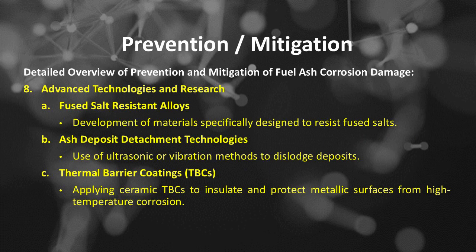Number 8 of prevention and mitigation of fuel ash corrosion damage is advanced technologies and research. Number A, fused salt-resistant alloys. Development of materials specifically designed to resist fused salts. Number B, ash deposit detachment technologies. Use of ultrasonic or vibration methods to dislodge deposits. Number C, thermal barrier coatings, TBCs. Applying ceramic TBCs to insulate and protect metallic surfaces from high-temperature corrosion.